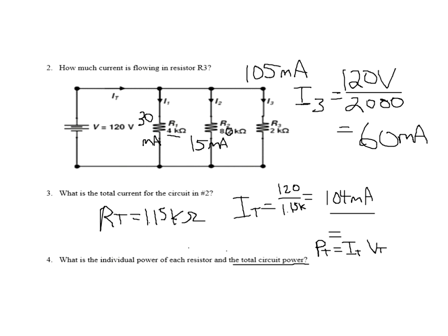And in this case, 104 milliamps times 120 volts. I'm doing this on my calculator. You should be doing it as well. I got about 12.5 watts.